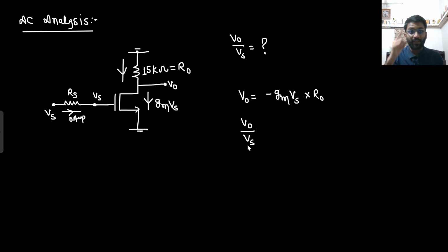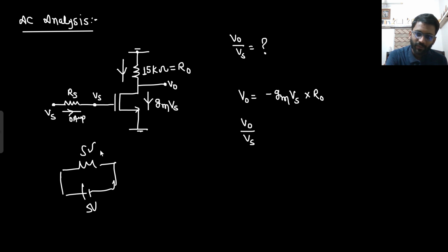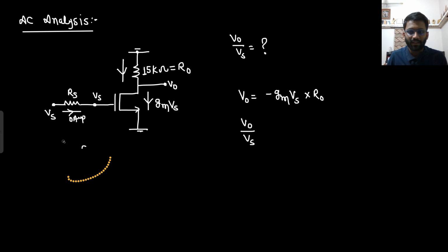Current always flows from high to low potential, but in a resistance, I need to make the statement clear. The statement that current flows from high to low potential, that is wrong. I hope you have studied this in network analysis. Since we are discussing this just as a small topic, if this is 5 volt, this is 5 ohm resistance, what is the current flowing? 1 ampere, right? Now people say the current flows from high to low potential. What is the potential difference here between these 2 points? 0 volt. What is the current flowing? 1 ampere. Even if there is 0 volt potential difference, current is flowing, that is 1 ampere. The current flows from high to low potential in a resistance, in an element, right? So this was not a matter of concern, I just explained a small point.